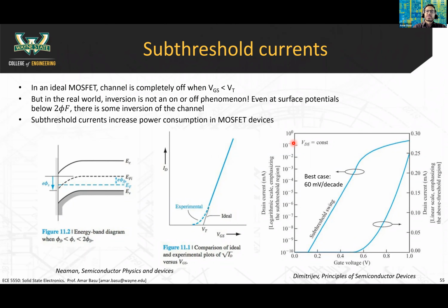Let's say your threshold voltage is 1 volt, and now in the new process we're expected to use gate voltages less than 1 volt. So then we're operating the transistor below the threshold voltage, and the transistor's never actually on. So think about that for a second. A lot of these low power computer chips operate in the subthreshold region, where the transistors are never actually completely on. So let's give some context for this.